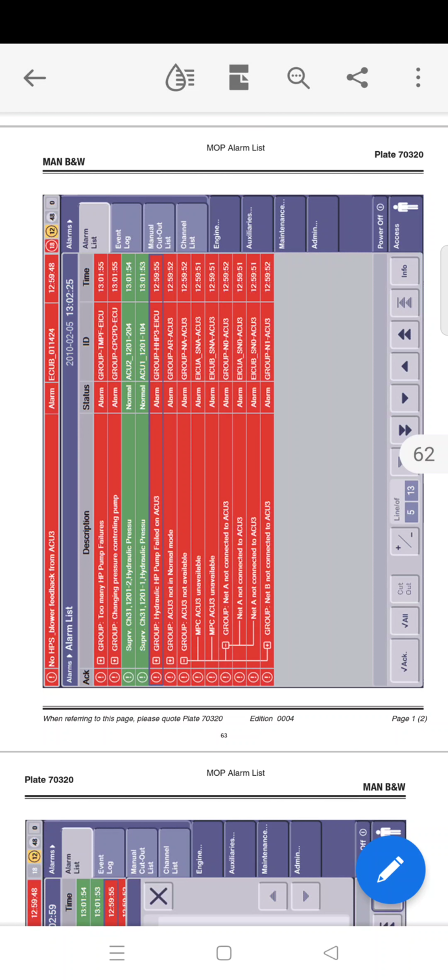Alarm system. The alarm system displays on the MOP panel are all related to the ME engine control system and thereby surveillance of the engine condition. Now the ordinary alarm system and the ME ECS alarm systems are connected and able to interact. This is caused by the use of common sensors for engine monitoring. That is, common sensors are used for indicating and detecting alarms as well as slowdown.